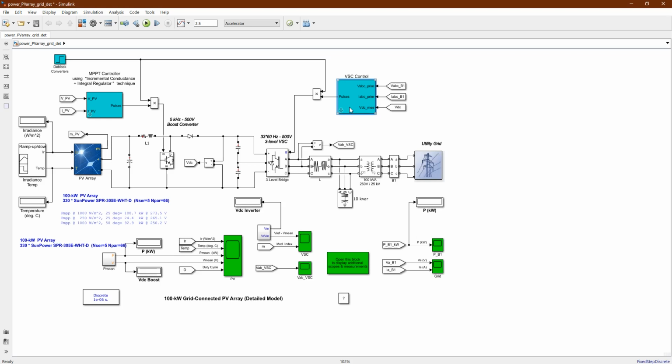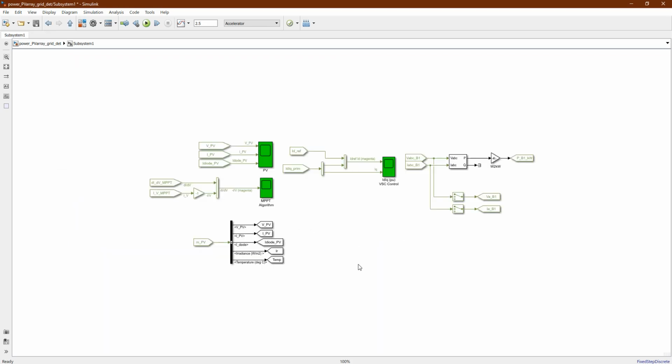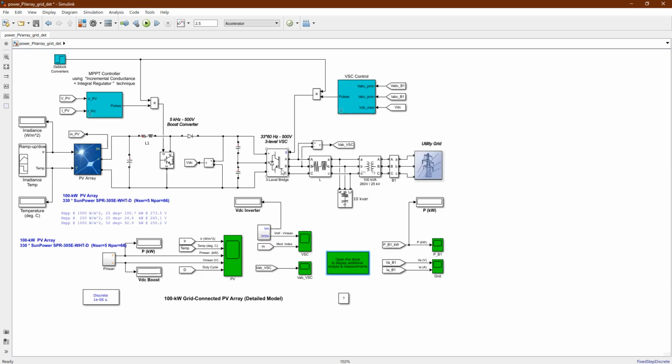One, the external loop, is used for regulating this DC link at 500 volt. The internal loop, which is a current controller, is used to control the output current to produce a pure sinusoidal current. And you'll find here this one, double click here, all of this are measurement ports.